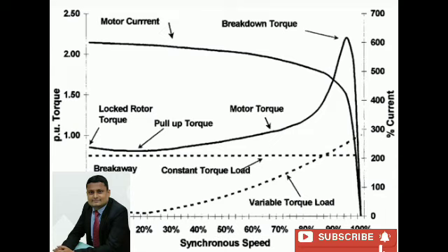Copper loss in end ring: mean diameter of the end ring DME is assumed as 4 to 6 cm less than that of the rotor. So DME equals DR minus 0.04 to 0.06. Mean length of the current path in the end ring LME equals pi DME.